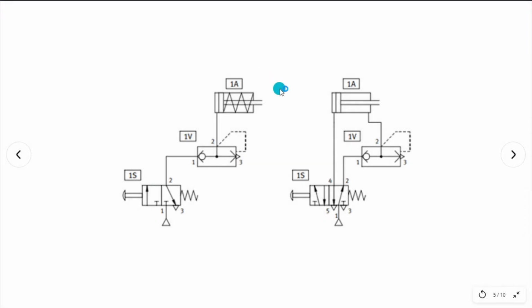So it is just like a normal direct actuation. But in the retraction part, the air pressure now will go back to the pipes, and then the airflow will go out to the environment through your exhaust valve. Instead of the air going all the way back to your input element before it exhausts, it will go out faster using the exhaust valve.